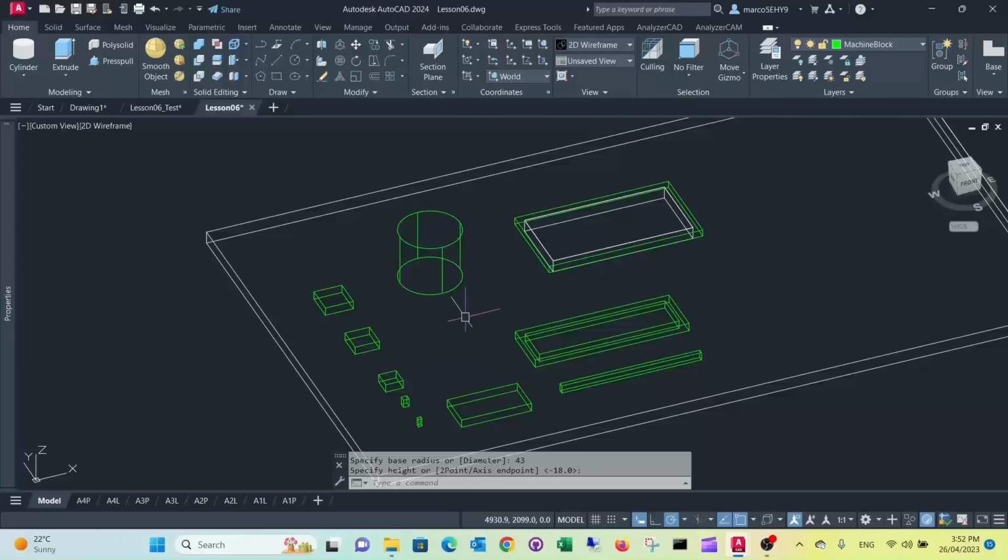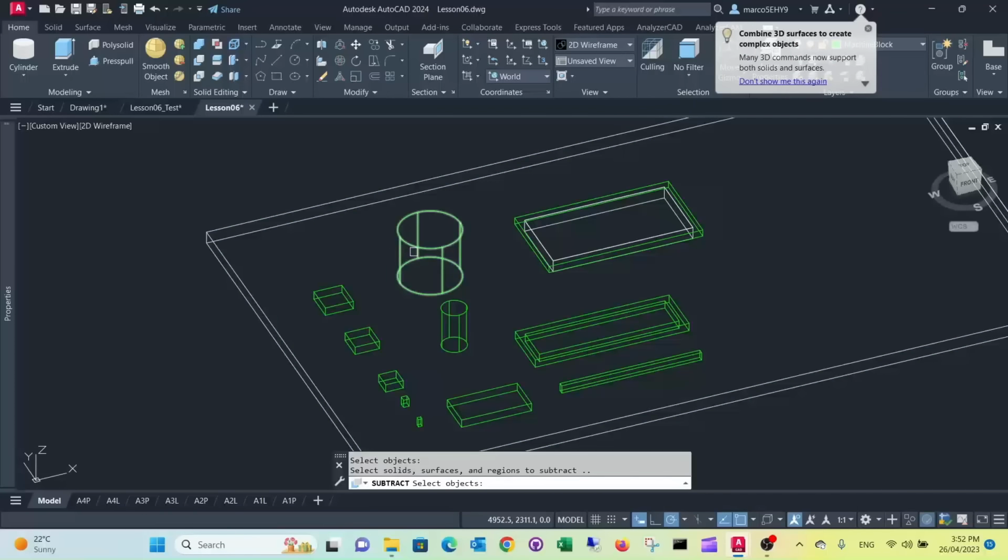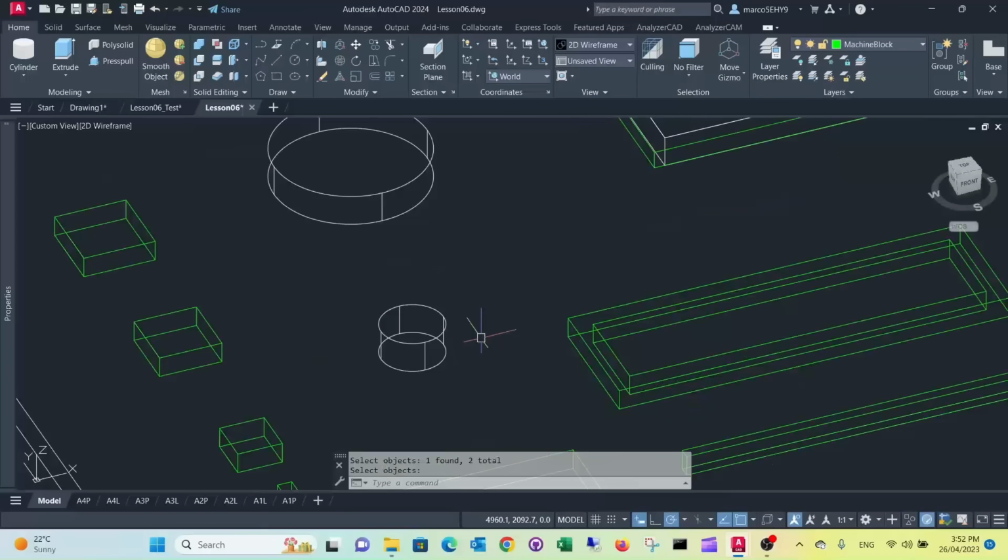Just pull it out of the board. Or you can do one that matches a drill. We have a 35mm drill there, so it's a 17.5 radius. Pull it out, and now we can make a subtraction. This is our board. Press enter, select subtracted parts, and here are our holes.